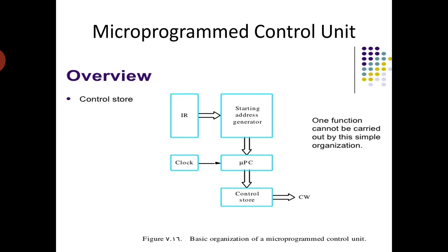Okay, microprogram counter. Every time the instruction register is loaded with a new instruction, meaning the instruction which is currently being executed is stored in the instruction register, the output of the block labeled starting address generator is loaded into the microprogram counter.